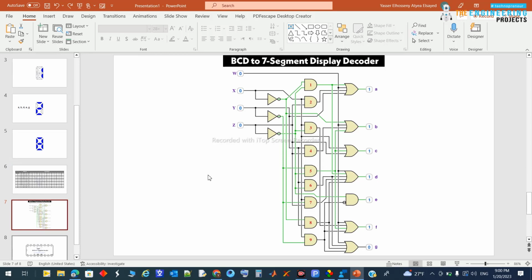In the beginning of the era of digital systems, we had to make a BCD to 7 segment decoder by implementing a couple of logic gates in this form, so that by having the input, you get the output of the decoder to see the status of each of the 7 LEDs that form one number from 0 to 9. That's complicated for electronics people. It's easy now, but before it was a very complicated logic calculation to implement such a decoder.